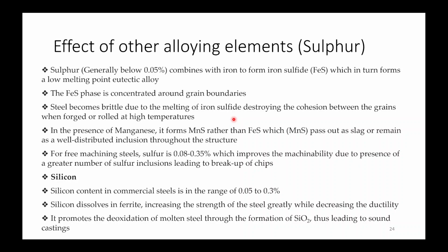It will be melting at grain boundaries, so your material won't have good properties. Okay, ma'am. Actually, these small amounts of elements will be around the grain boundaries, I mean the manganese, chromium that we add, they'll be forming around the grain boundaries. Manganese you are adding to prevent formation of FeS. If MnS is forming, it is better for your steel, because MnS can be either removed by slag, or it will be in the form of inclusion, then it is better. While FeS, when it is forming, goes to grain boundaries.